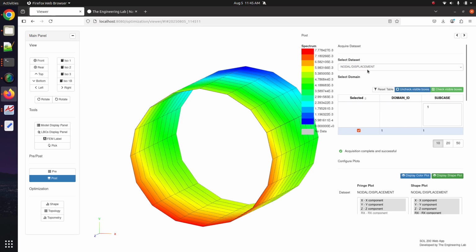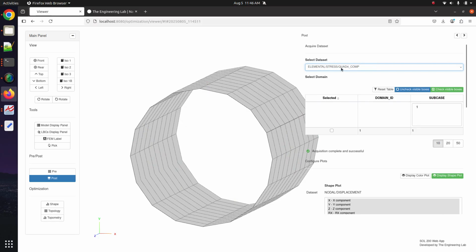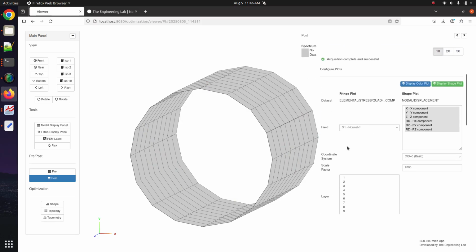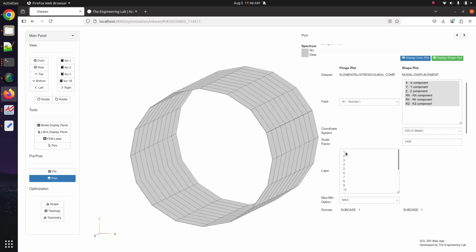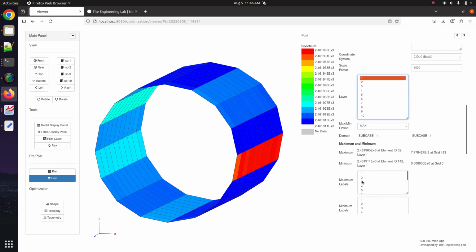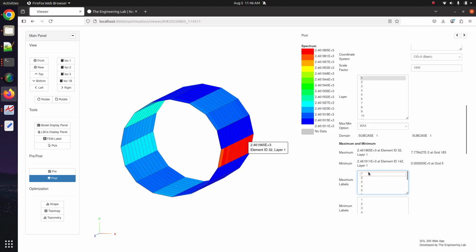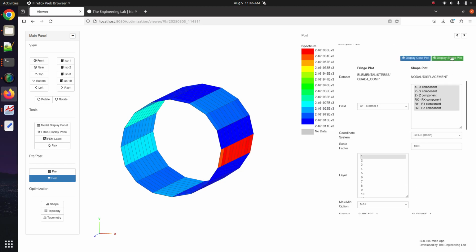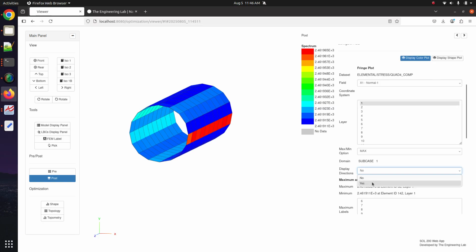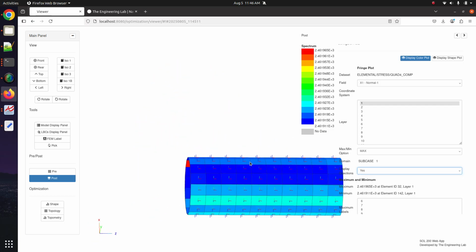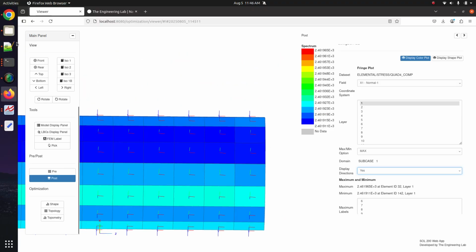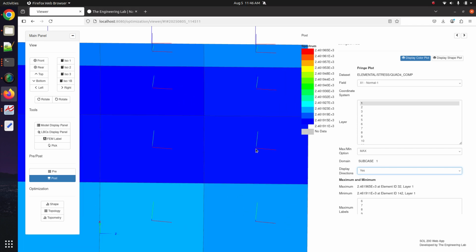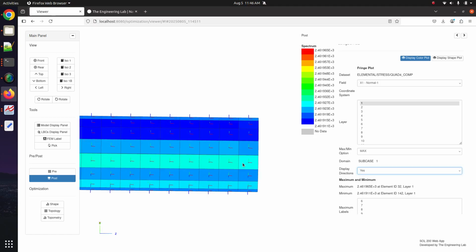Okay, let's look at some apply stresses. I believe that's available here. So let's go ahead and select the stress quad 4 comp option. Let's go ahead and select subcase 1. Now, when you mark the checkbox, you are not going to see results yet. You have to tell it what layer you want results for. So maybe you want to look at results for layer 1. Let's go ahead and pick maybe the layer, or actually I don't want that. Let me see. Right, let's turn off the deformations for a moment. When you turn off the deformations, you can then display the directions for that layer. So I say yes. You can see this is the direction of that layer. And then I forget what the first angle was. It was 45 degrees. I think there might be a bug here. This first layer should be 45 degrees, but this does not look like, oh, you know what? I think I know why.